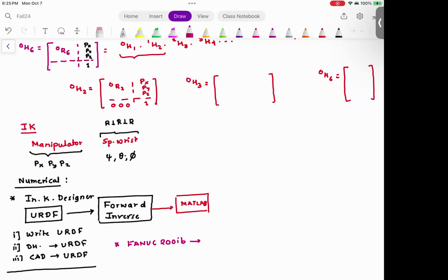You can click on each link described in that robot, and it will show you the link lengths. You can change these link lengths to correspond to the 200iD, because the robot configuration for the 200iB and 200iD is the same. All of this is inside the URDF file.